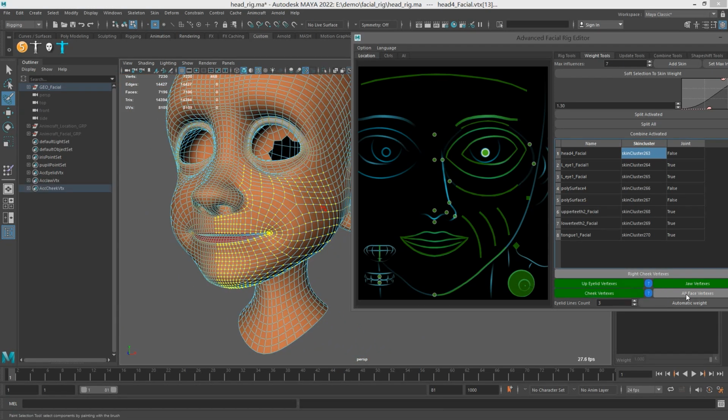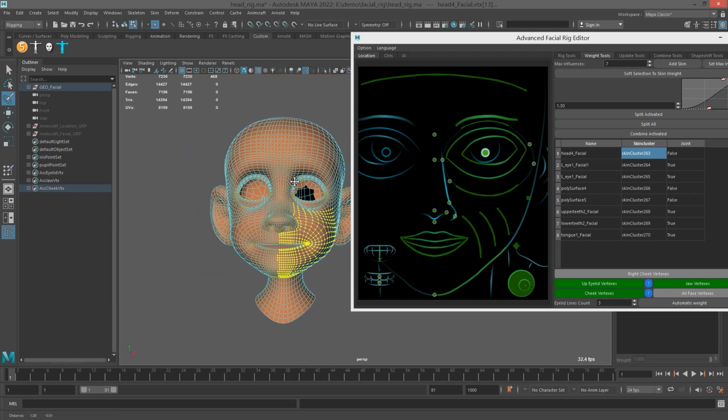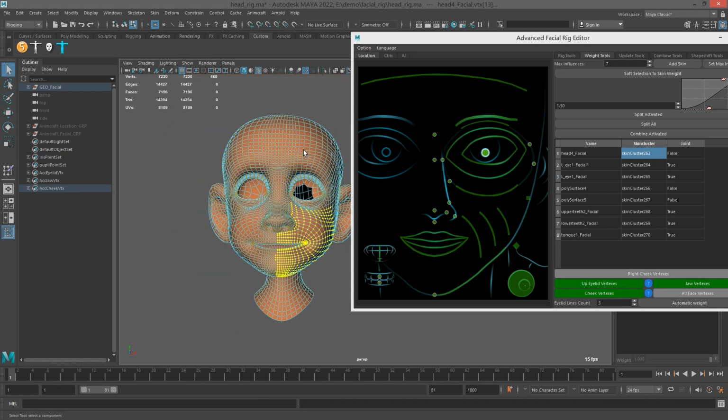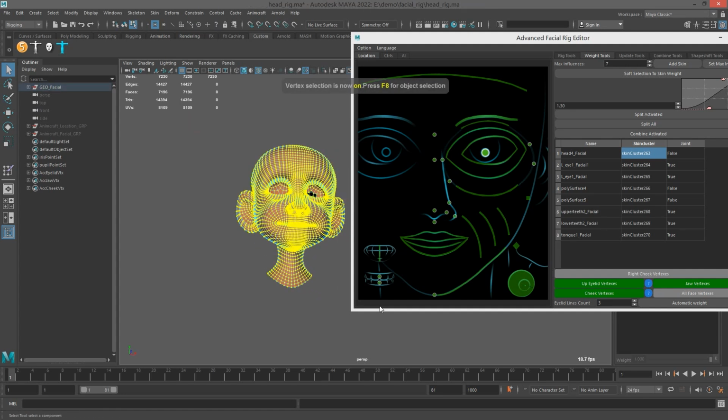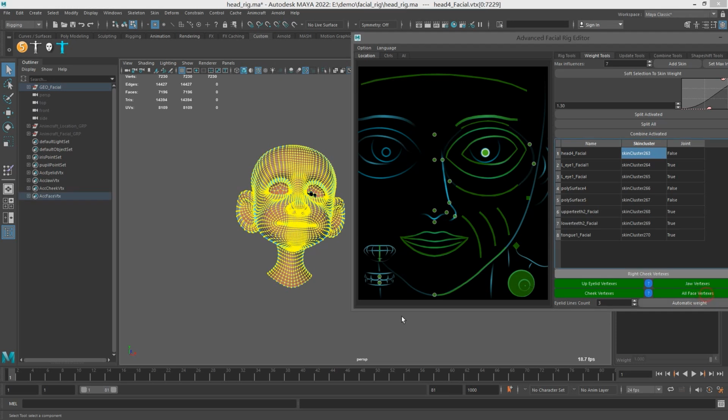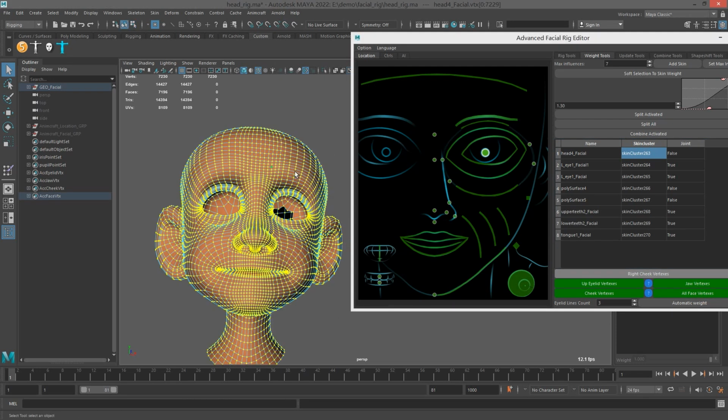Next, this is for the vertices of the entire face. Alright. If the head and body are combined, when it performs a calculation, it might be slow. So we only need to select the part that needs weight calculation, for this example the head. Just select all points on the head and add it here. Fine, it's done.